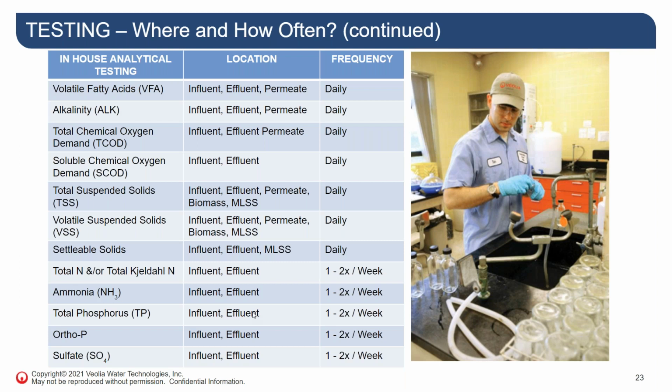As much as it says wastewater and not wastewater and solids, solids are always in that wastewater. So we need to know what contribution they're making to the production of biogas, and if they are harming the system by not breaking down and washing out. So that's partially told to us by the difference between the total and soluble COD.